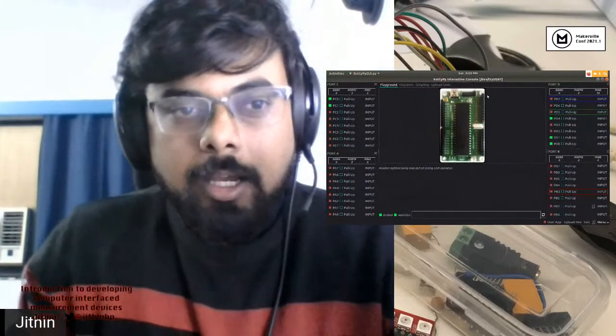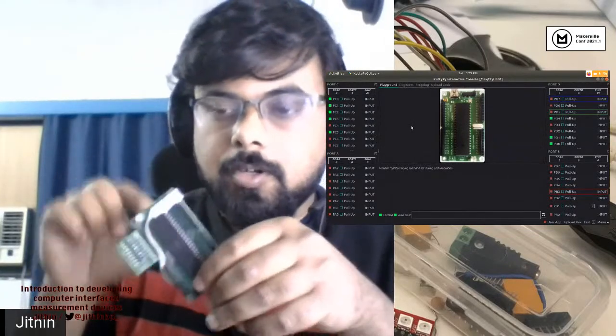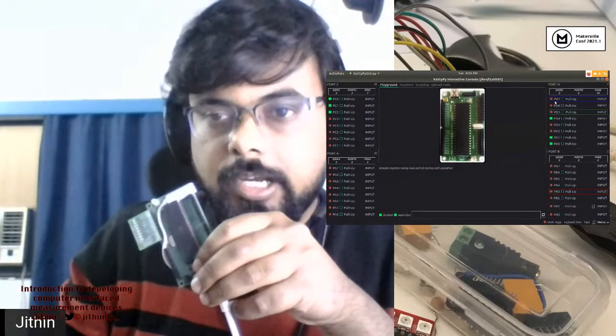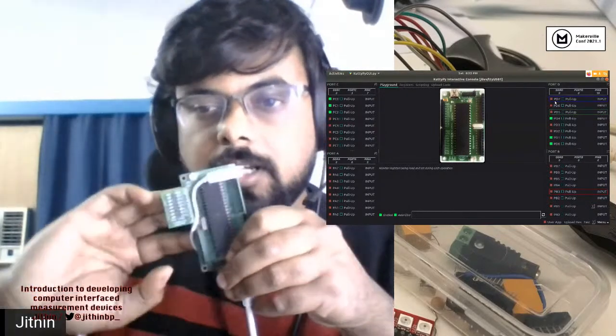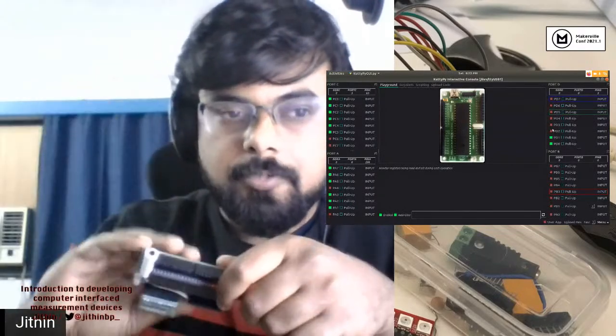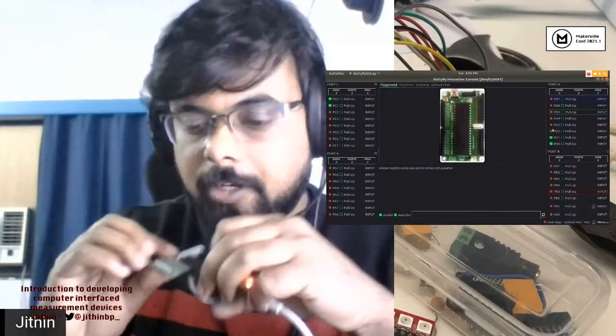Yeah, and what you see here is the live status of every input pin here. So I have 32 pins, and all of these are shown either as low, which is red, or as high, which is green. Now, if I touch this, you can see them fluctuating in real time. Okay, so it's stray charges from my fingers actually causing this, so it's real data coming here on the fly.